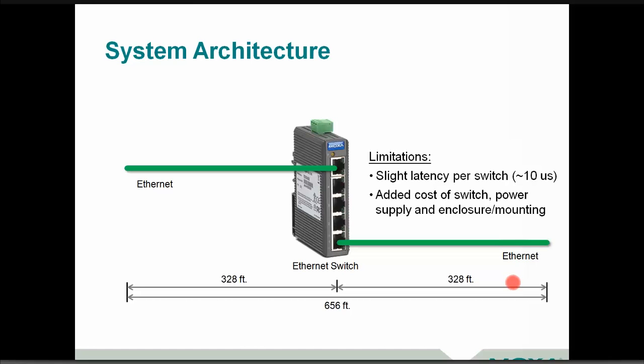Sometimes the simple things are overlooked, and there's really very little impact to your application to go far enough to do that. Now, some people might ask, well, hey, Paul, this is great. Could I do this a couple times? And absolutely, you could actually cascade a couple of switches by going into a switch and out, and back into a switch and out. Two caveats on this: there is a little bit of latency, and generally you're seeing about 10 microseconds of delay through each switch.